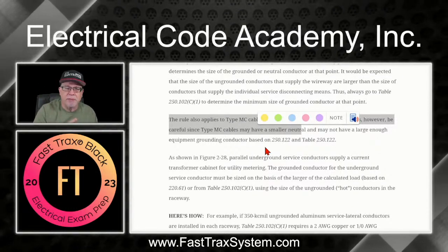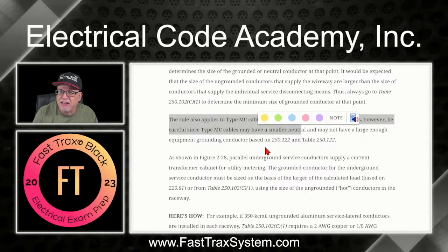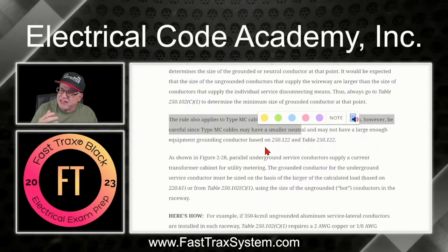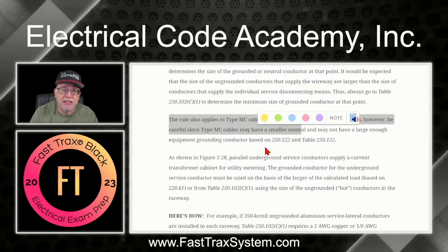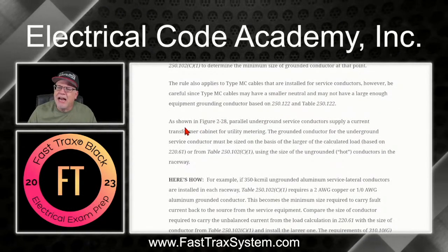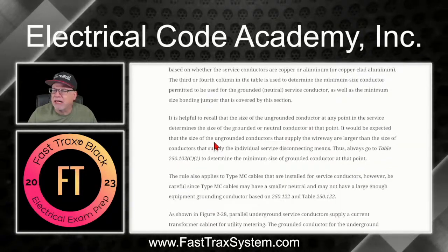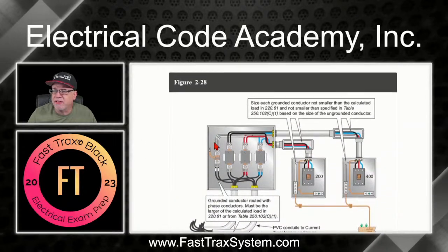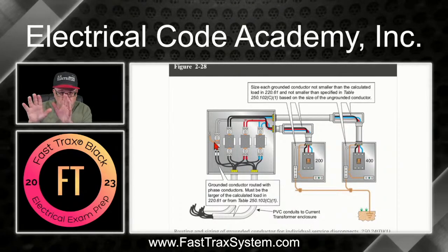Okay, this is just a reminder, when you're sizing it, don't just go buy a cable and assume that the grounded conductor or even the equipment grounding conductor is properly sized. Just be careful when you're buying off the shelf, okay? All right, now, as shown in figure 2-28, and again, I'll just reiterate it, there you go, to kind of get you an idea of what we're talking about.